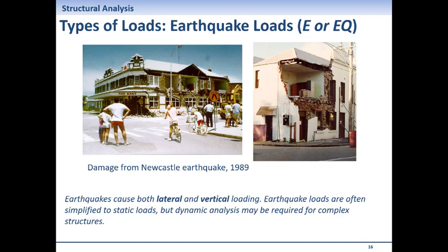Each and every standard that you pick up to use, one of the first pages is called scope. That's another important page, it's normally one page. It tells you when and where you can and you cannot use that particular standard. For example, wind load, 1170.2, I think there's a limit of 200 meters, I might be wrong, but it's got a limit on the height of the building. If the building is higher than that, you can't really use that standard. You have to use another way of estimating the load.